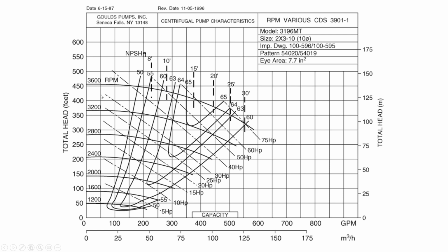And this is the same pump. If instead of being spun at 3,600 RPM, you spin that pump with a motor that goes 3,200 RPM, then it only has a total cutoff head of about 360 feet. And then declining head can be added as the flow rate goes up. So this is a single pump, but they're showing what if you matched it with different motors that operate at a variety of different speeds, or if you had something called a variable frequency drive that changes the characteristics of the electricity going into the motor, and with that changes the RPM that it operates. So one of the things you can get out of these manufacturer-provided pump curves is just how the pump operates at a variety of different rotational rates.